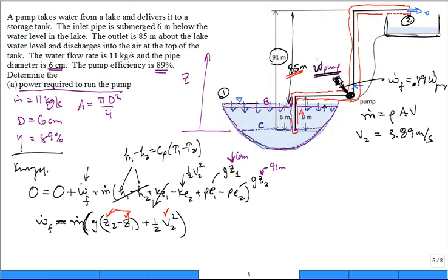And then you had the mass flow rate, 11. So let me kind of bust this up. 11 kilograms per second. This first component is 9.81 times 85. It's 833.9 plus 7.58, and that's meters squared per second squared. And it converts to so many kilojoules per kilogram.